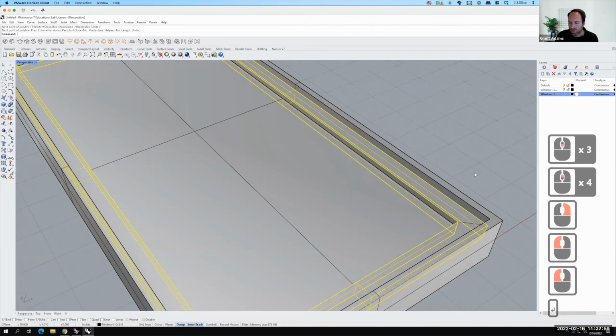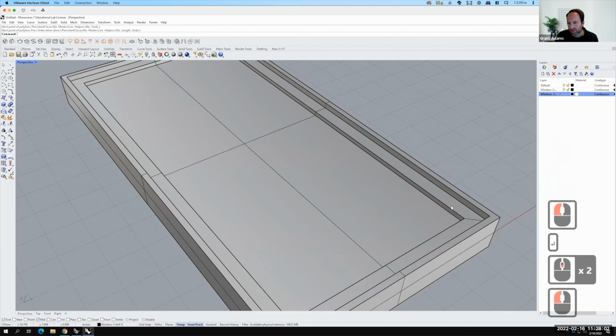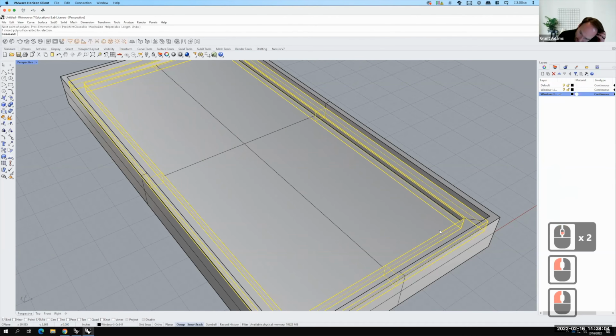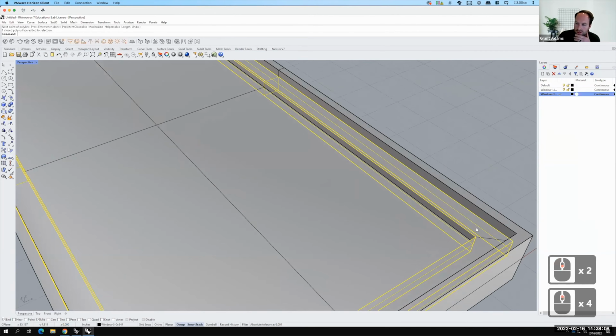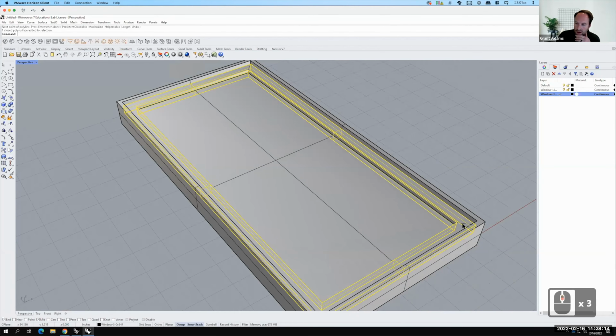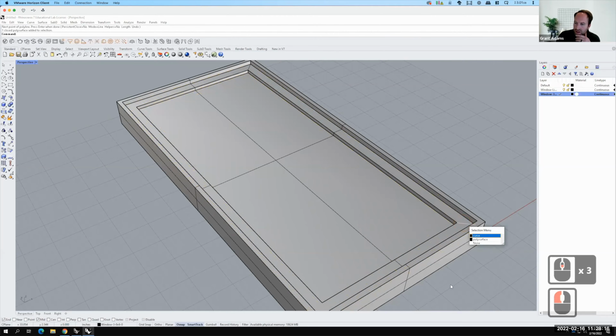And if I want to split this, I have some complicating factors here. This is currently a solid, so it goes all the way around. If I'm splitting just the top surface, then I need to explode the solid first. If I'm splitting the whole 3D object, then this line is not nearly thick enough. I need to make sure that it's actually a plane that goes through my objects. So there's really two options here. I'll show you both methods just so you can see it.